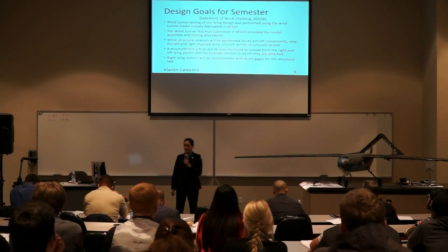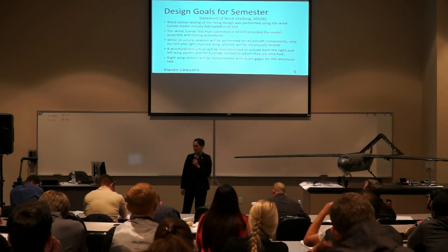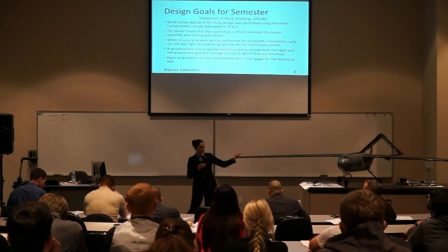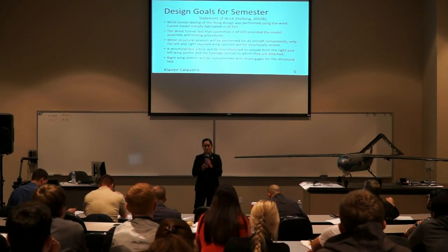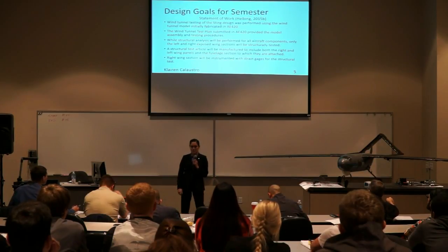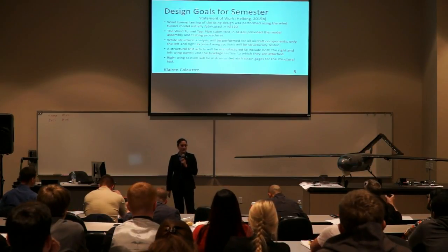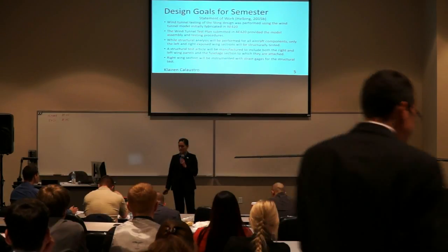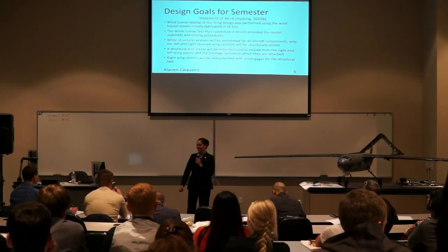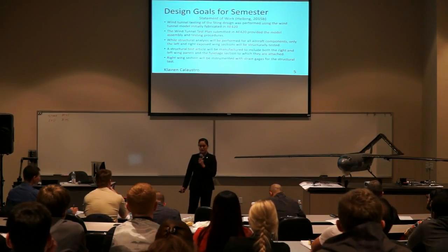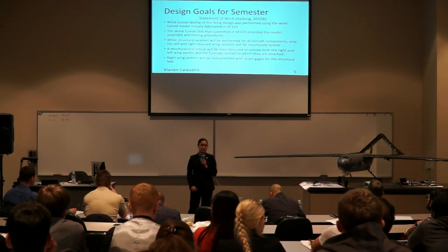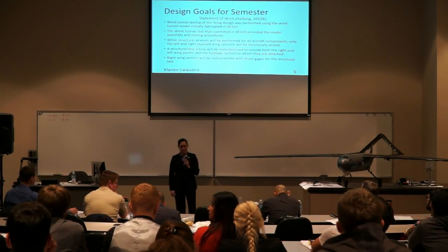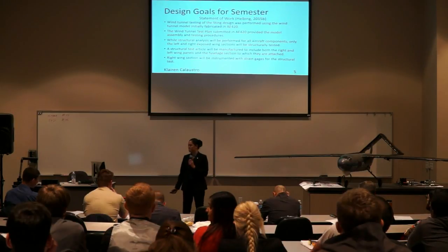So here are design goals for the semester. This was driven by the statement of work provided by Professor Helbling. So we were to create this STA, like I mentioned. It'll be inverted, and then it'll be instrumented in the right wing with strain gauges and rosette strain gauges as well to calculate the strain in the aircraft with an 80% load of maximum loading. And then after our structural testing, it's not a requirement of the class, but flight test was a goal of ours, and we were actually able to achieve that, and we'll show you later in the slides.